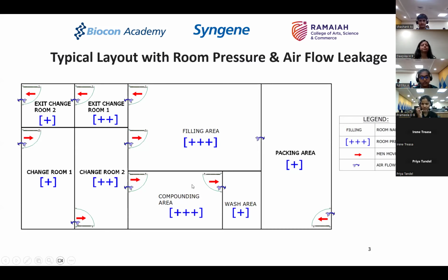Now, coming back to this, as I explained, the compounding area is at the most positive pressure when compared to the adjacent two rooms. If you see, the compounding area air volume pumped was about 1000 CFM, out of which 50 CFM is going as exfiltration towards the wash area and 50 CFM is going as exfiltration towards the change room. Thereby, even though I am pumping in 1000 CFM, I am only taking out 900 CFM as the return. Okay.